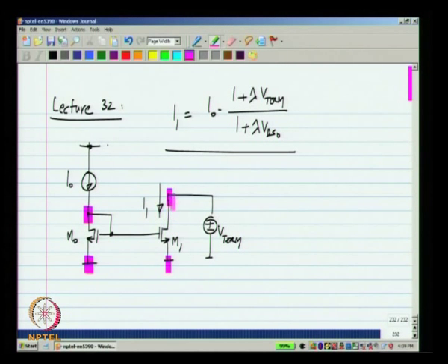If I want the output to be closer to an ideal current source, I would like to have a higher incremental output resistance for the current source. In fact, the current source would ideally have an incremental resistance of infinity. Now, I know my cascode trick. So, what I will do is take this current and have a common gate structure on top of it. Let me bias it with some Vg0, which will maintain all transistors in saturation region. Or let me call this MC1.